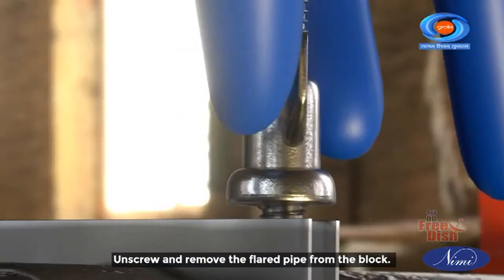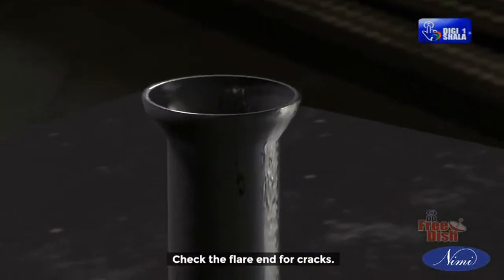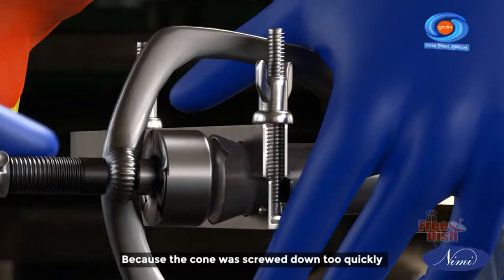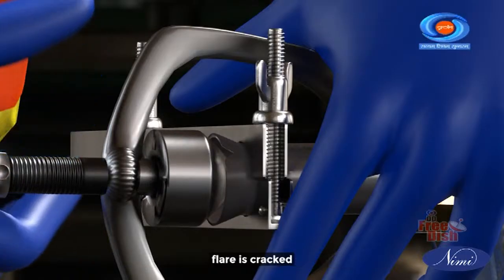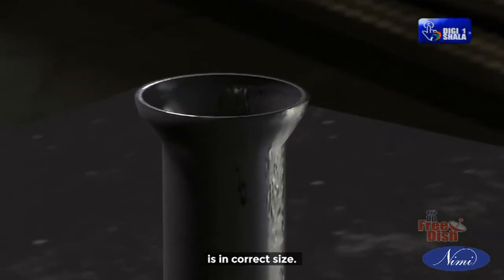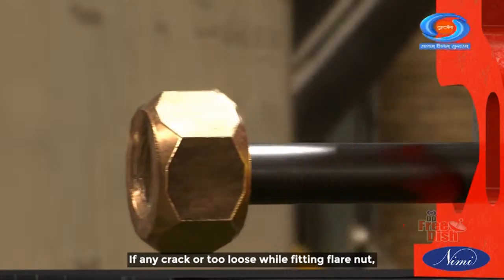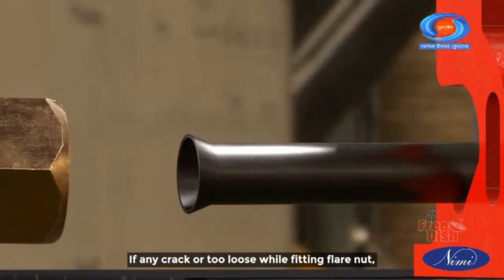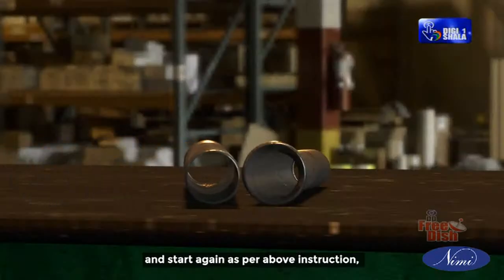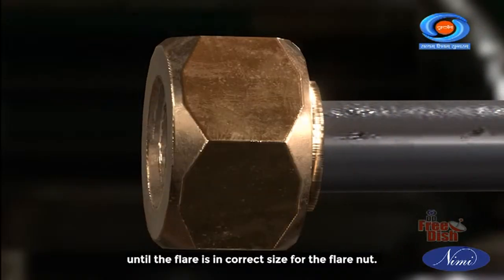Unscrew and remove the flared pipe from the block. Check the flare end for cracks. Note: because the cone was screwed down too quickly, the flare is cracked. Make sure that the flare is the correct size. If there is any crack, or it is too loose while fitting the flare nut, cut off the flare and start again as per the above instructions until the flare is the correct size for the flare nut.